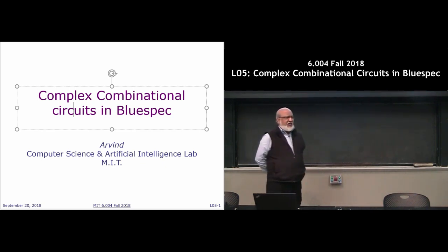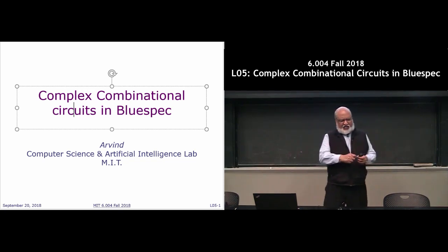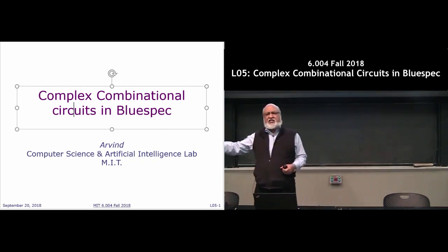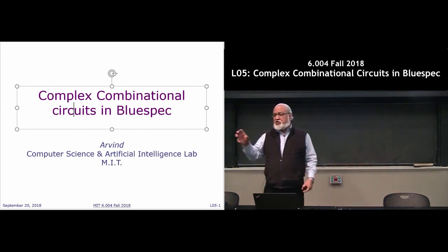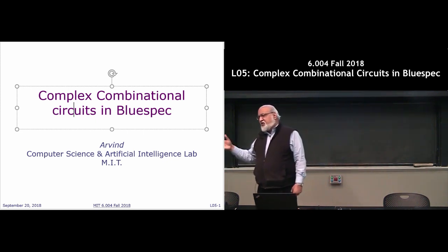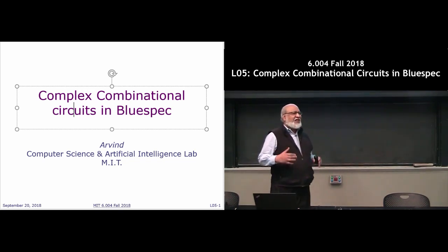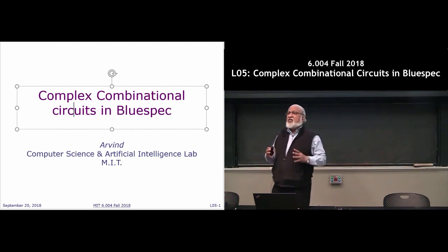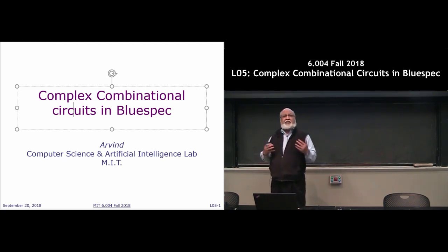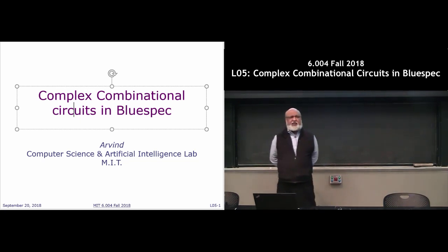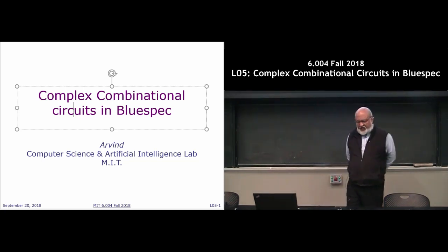Functions are the same way. You may have heard that this function calls that function, and stacks and this and that. That's not how functions are going to behave here. Here, you take a function and you say, this function has a circuit corresponding to it, so you plop that circuit. In the jargon, it's often called inline substitution. You replace the function call with whatever its body was. And this is all being done at compile time, so there are no dynamic function calls. Everything is going to happen statically.